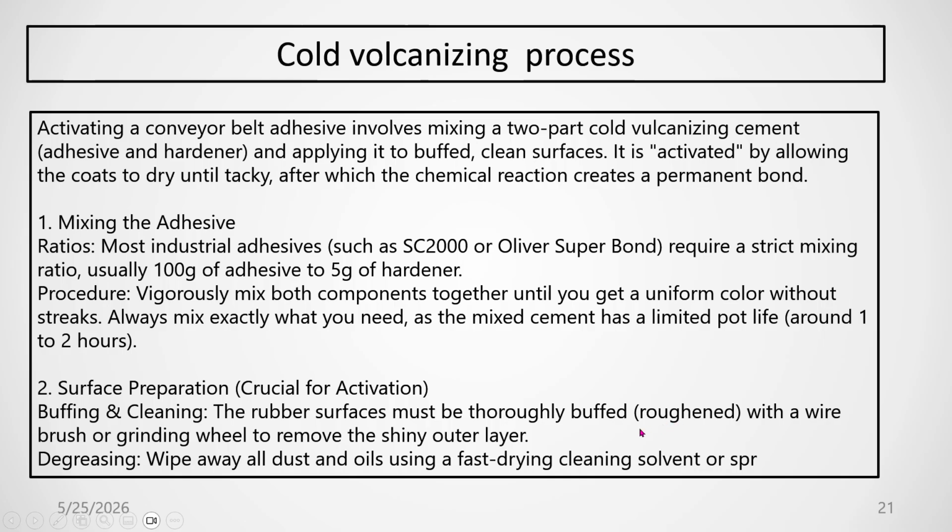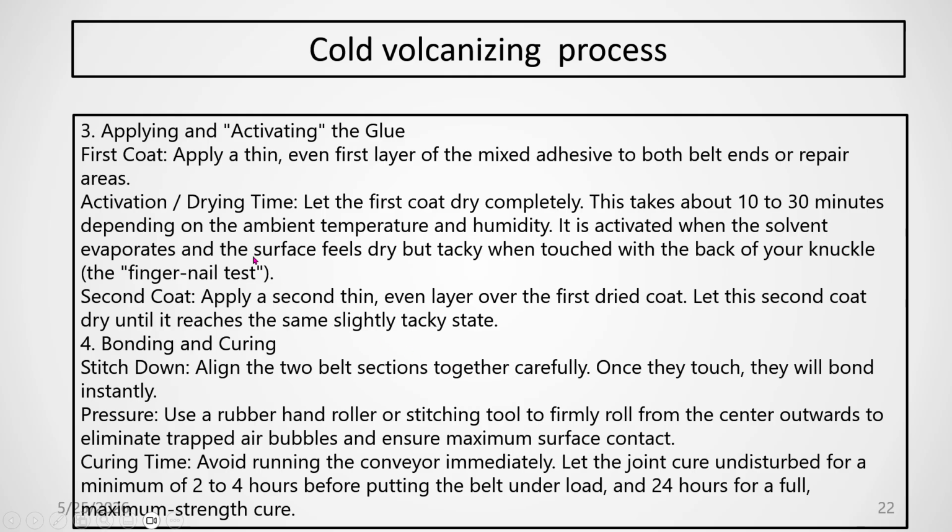Buffing: you have to roughen the surface with a wire brush and grinding wheel to remove the shiny outside layer, and then degrease it to remove oil etc. The climate should be dry, and then activate the glue, which means the cold vulcanizing process.